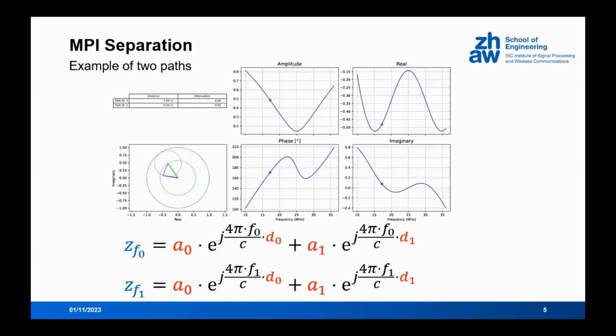Because in reality you have measurement noise, and also the components of the time-of-flight camera are frequency dependent, you cannot only measure at two frequencies and get a good result. Instead, in our case, we had to measure at least 5 different frequencies to get good results.